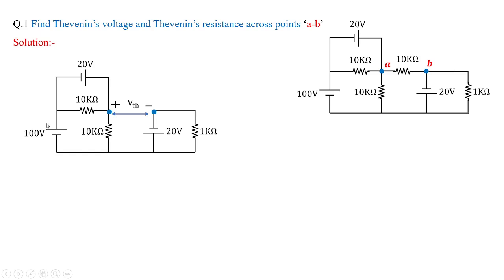So if at all I take the KVL in the loop, I can get the total voltage of open circuit as, you can see I have taken minus 100 here, then minus 20 is replicated as it is here, plus minus voltage terminals I have taken in my convention way, and on the flip side we have minus 20 and that is equated to 0. So here if at all you take the terminals voltage, it will be coming around 140 volts.